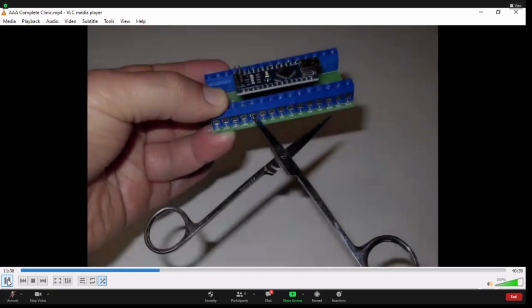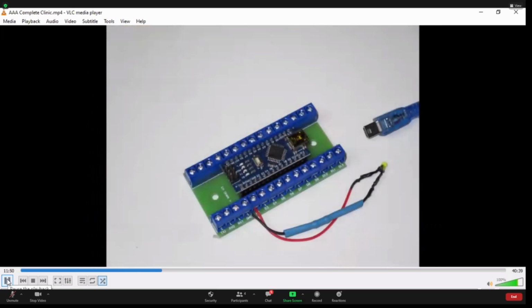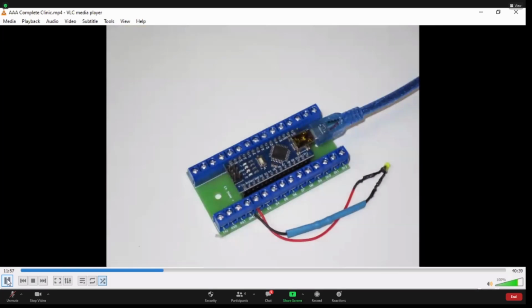If the wire doesn't want to go in, take the pointy end of some decal scissors or some other small object and place it in the socket and raise the flap on the inside. Now insert the black end into the socket labeled GND. This is the electrical ground. This completes all the required electrical connections, so we can plug the USB cable back into the Arduino.